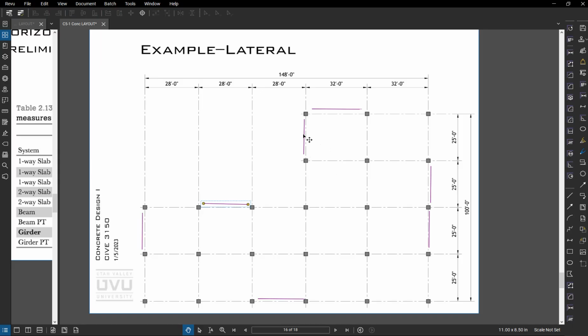If that blocks a great view for an office, say the mountains are up here or the ocean or something cool to look at, maybe you pull these to the interior or back over to here. Lots of options. You could even do something like this where the shear wall is on the interior of the building and you can have a fairly large opening that you could walk between this space and this space.